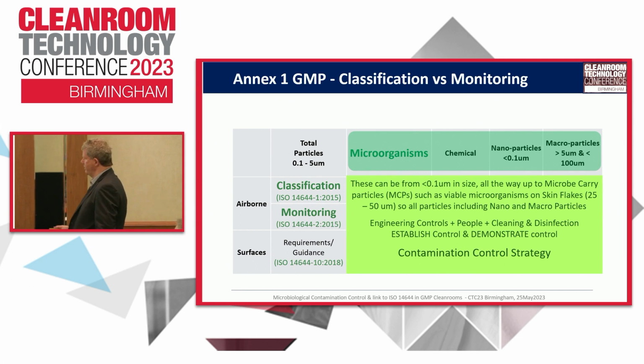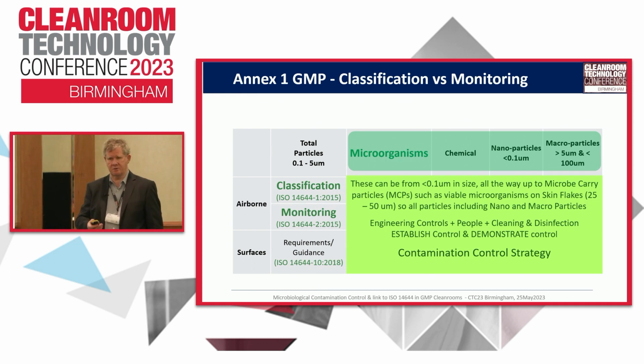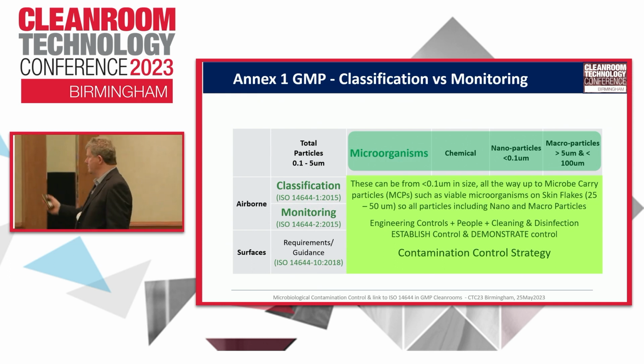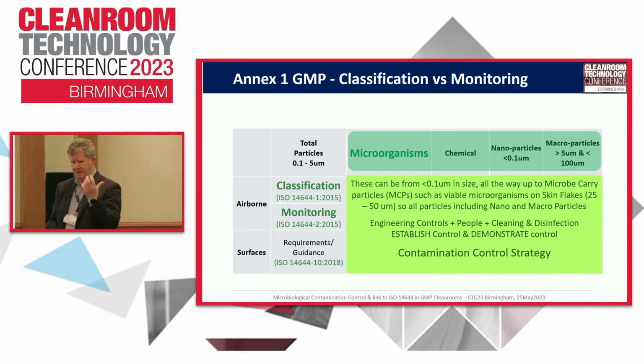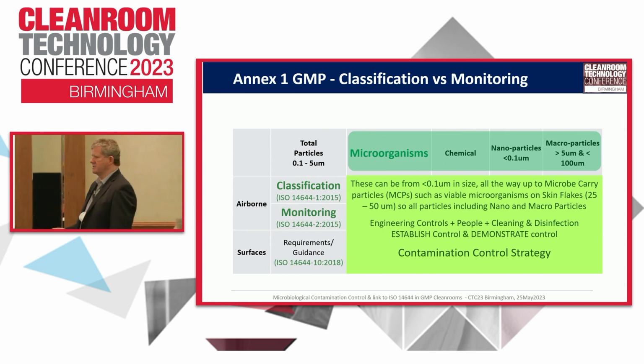Okay, and again, from a microbiological perspective, you can be from 0.1 microns, where viruses are around that range, all the way up to yeasts and molds. The control of microorganisms is through engineering controls, people controls, gowning, and cleaning and disinfection. So notice I'm going around, doing a deep dive, going top down and bottom up, to change the way you think about clean rooms.